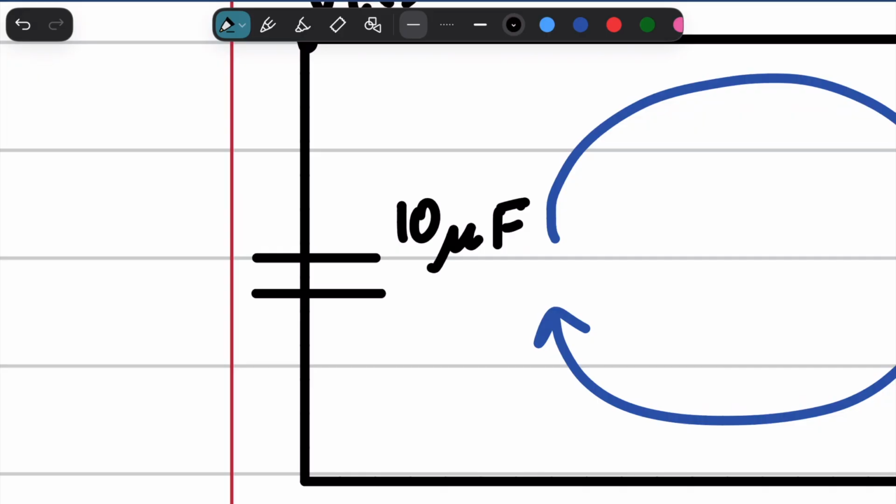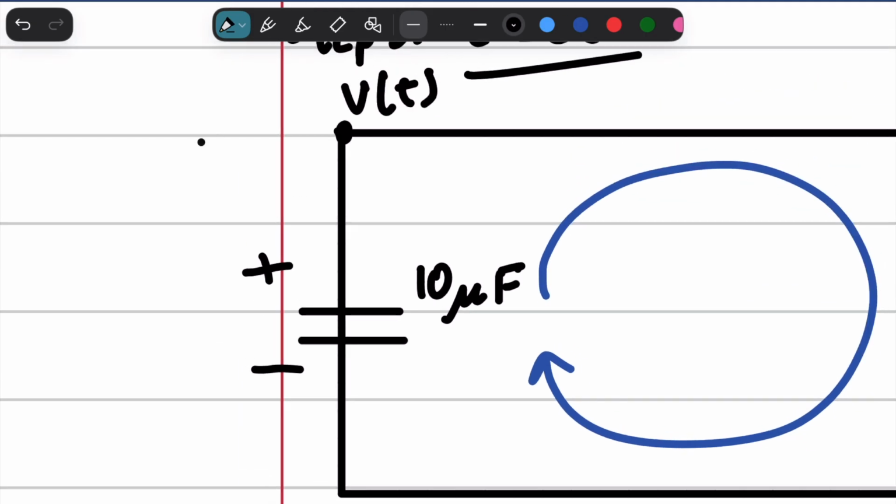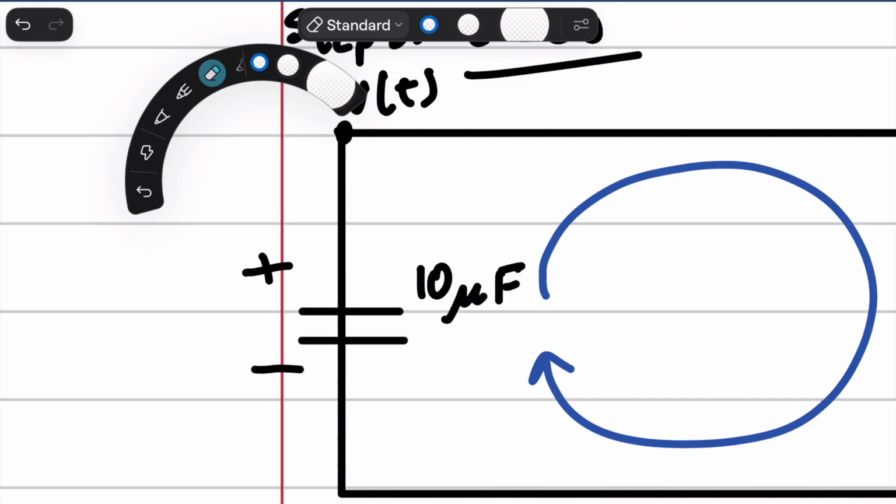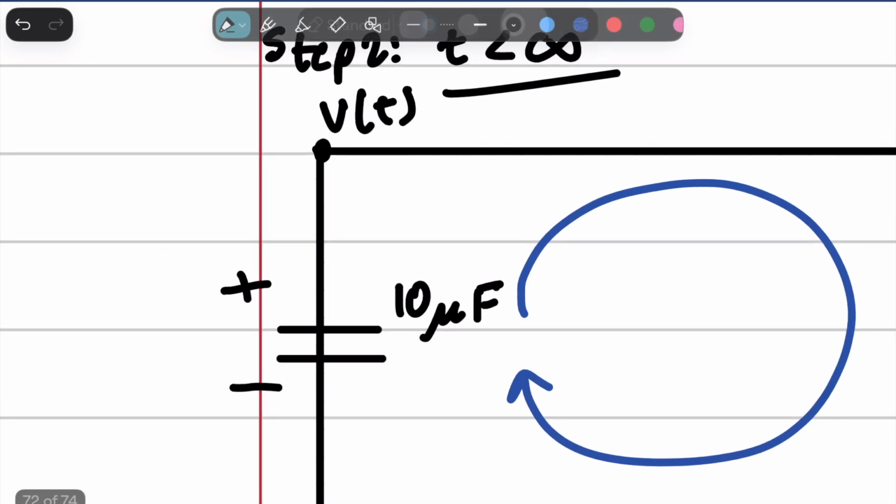One piece of that information is, what is the polarity of this capacitor? The polarity of this capacitor is plus on top and minus on bottom. Why? Because we had a voltage difference across it when it was charging in the negative infinity portion. It was charging with the 5 volts right here and ground being here.